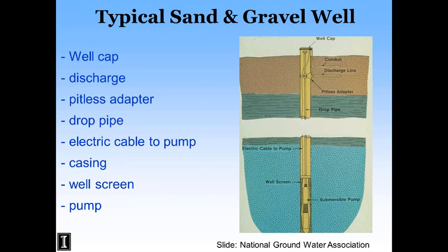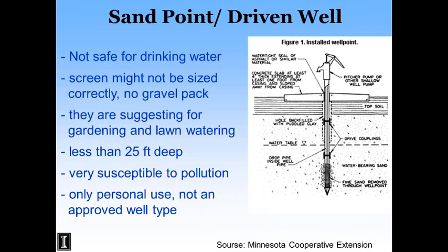And there are a lot of older wells that are still in pits, and I'll show an example in a minute. But if you do have a well that's in a pit, there's a lot of risk there. Water standing in the pit can eventually lead to flow around the casing and start working its way down as it dissolves some of the soil material. Not being above the surface makes it prone to flooding if there's such an event, which can cause electrical problems or cause contamination problems. And so well pits just need to be eliminated.